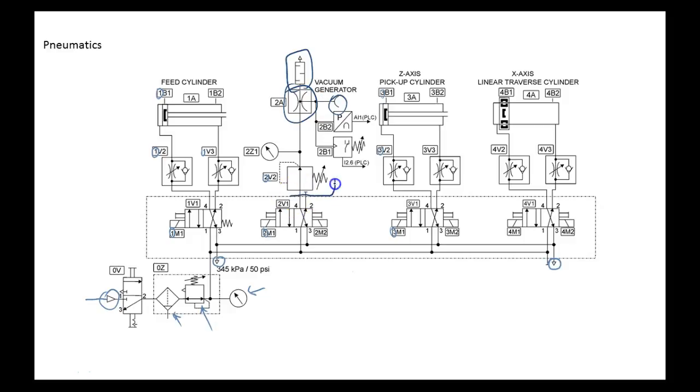This is the pressure valve. This is a pressure control valve. We're using that to control the vacuum, because the pressure is directly related to the vacuum, right? So we can use this. This is a pressure switch. It looks like it's got two types. This right here looks like we can adjust; this is the adjustable pressure switch, and this one right here is not.